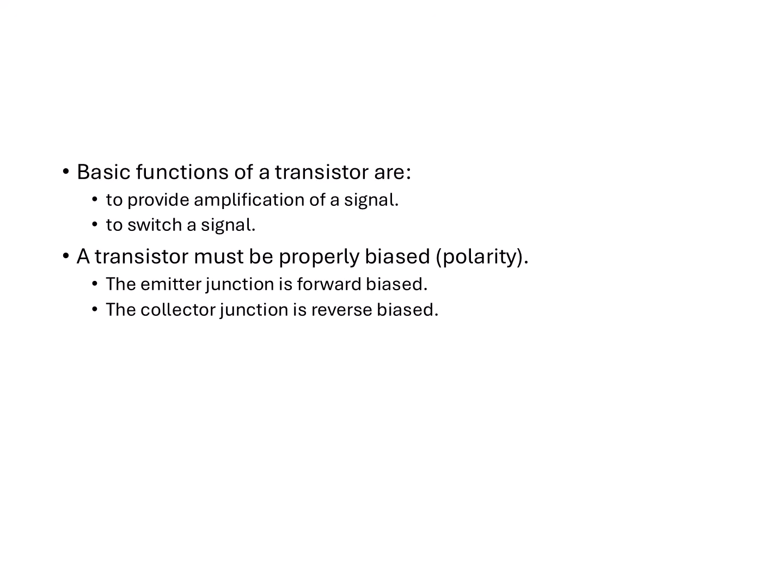The main functions of a transistor are to amplify electrical signals and act as an electronic switch. It uses a small voltage or current at one terminal to control a much larger flow of electricity through the other terminals. Transistor biasing is the process of supplying direct current, DC voltages, to set a stable operating point, or Q point, so the transistor can amplify signals without distortion. This is done using specific resistor networks like voltage dividers, fixed bias, and collector feedback.